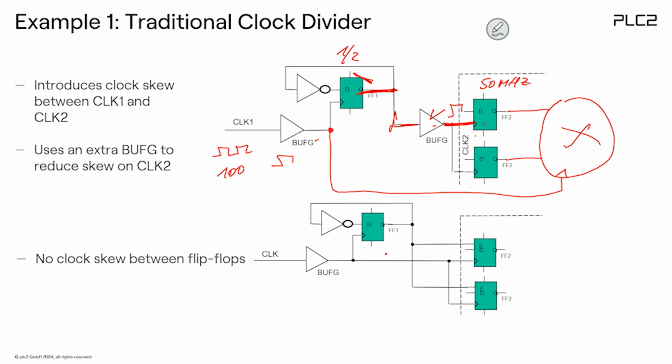Do this. That's very easy. Just use this as enable now. Now it looks like this. This is your master clock here. Now this enable signal looks like this. This means this flip-flop will be clocked in this case right here, so we really don't care about the delay.